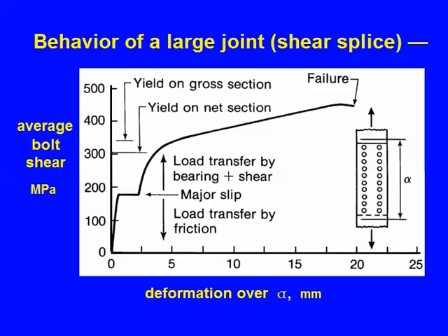So we keep on with the loading, and the initial region is reasonably elastic here. But things start to yield, and it starts turning over, and then there's some strain hardening going on, and ultimately there's failure. What other information can we get out of this? What's failure? Oh, you know, fracture. Fracture, things have fallen apart, and we would all agree that we can't go past that point. It would represent a limit, however.